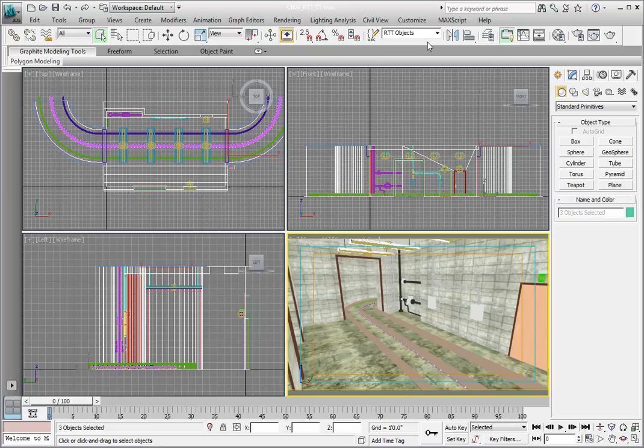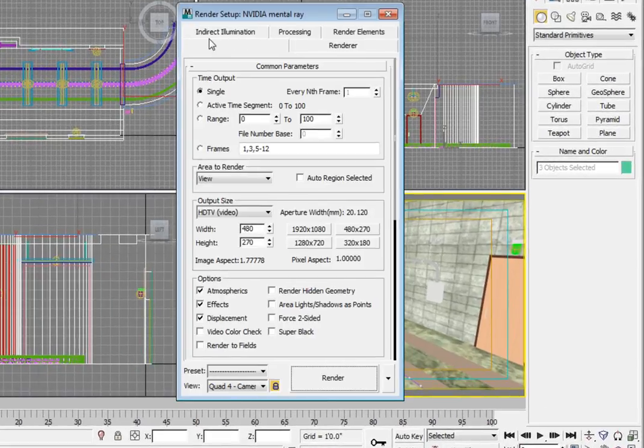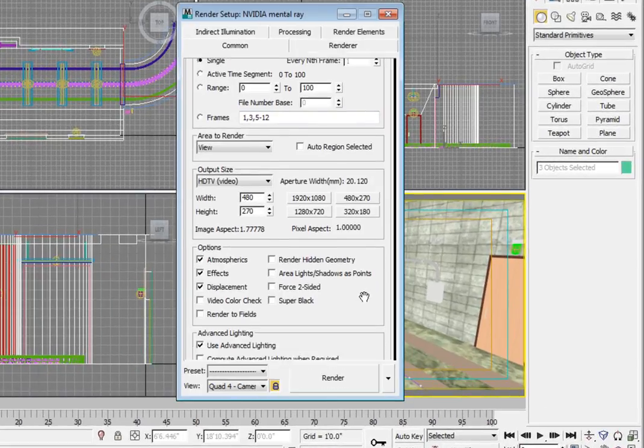It will make saving the Render to Texture files simpler if we first configure the render output file that saves to the hard drive. Click Render Setup from the main toolbar. Navigate to the Common panel. Scroll down until you see the Render Output area.